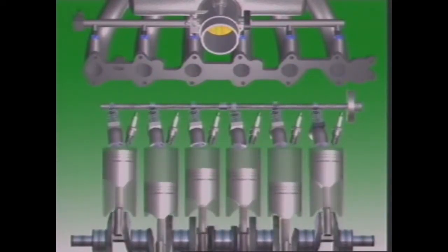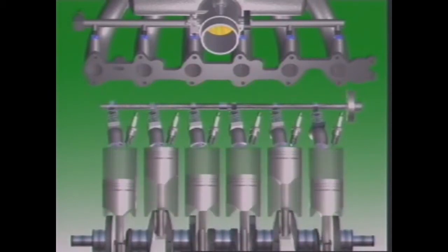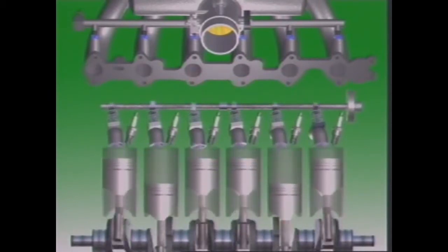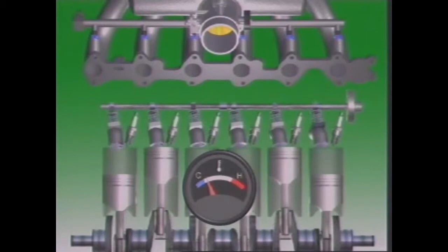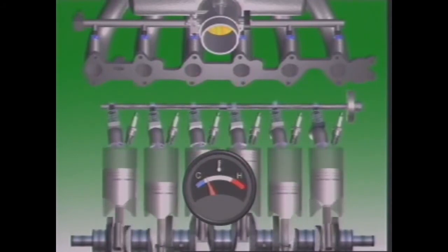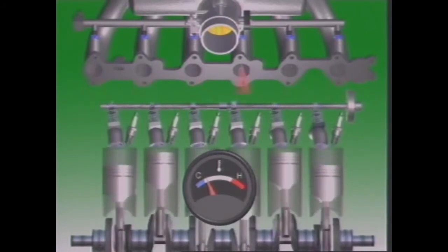Alternatively, simultaneous injection may be used during cranking and also in the warm-up period. Once a preset temperature is reached, the control unit changes to sequential mode.